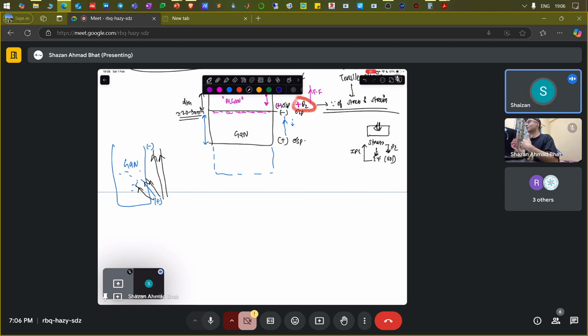Basically the electric field has electric field lines. You consider them as a field. So I should say a weak field basically remains. The weak field remains in case of a thick gallium nitride. If a thick gallium nitride layer is used, basically there is no field inside this device. There's a very weak field inside the thick region of this gallium nitride.